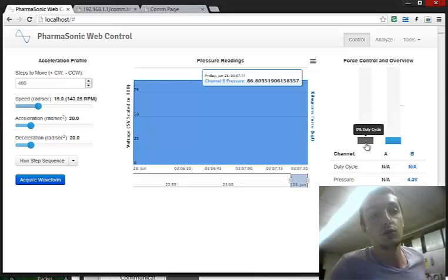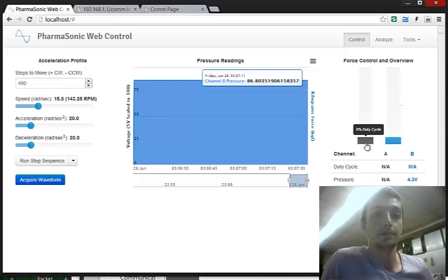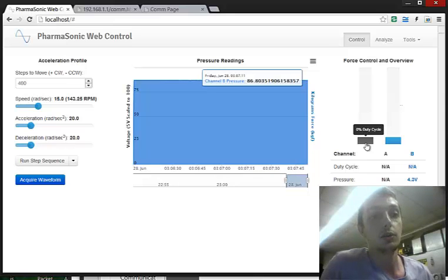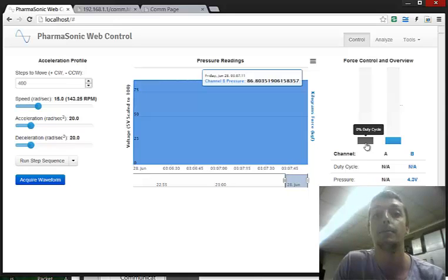There are a few pins on the Arduino that you can use to control the width of each pulse from a value of 0, which would just be flat and low, and 255 would be a completely high pulse, and something in the middle would be 50% high, 50% low.